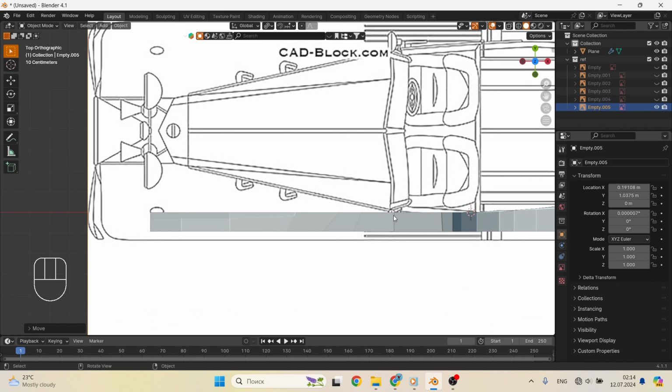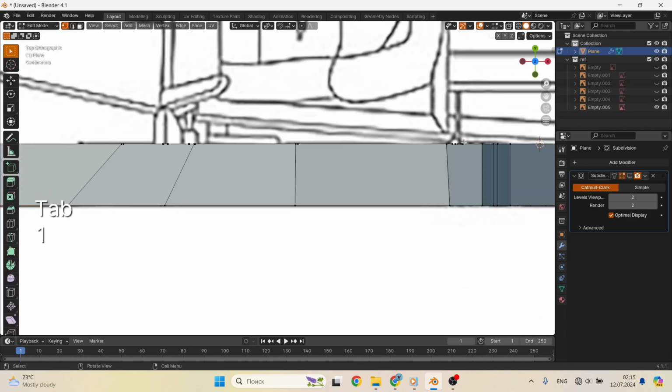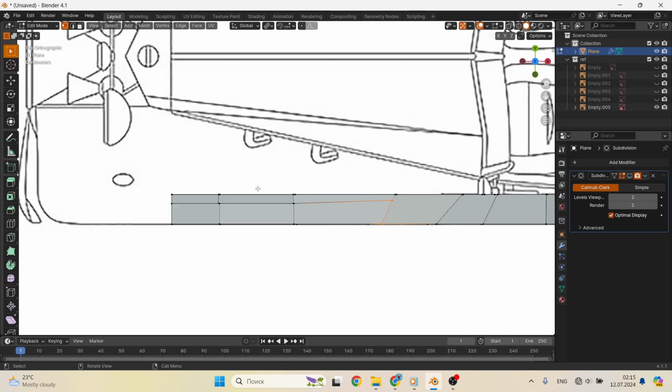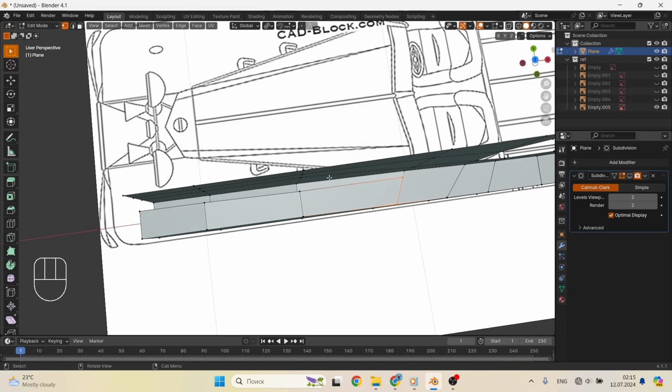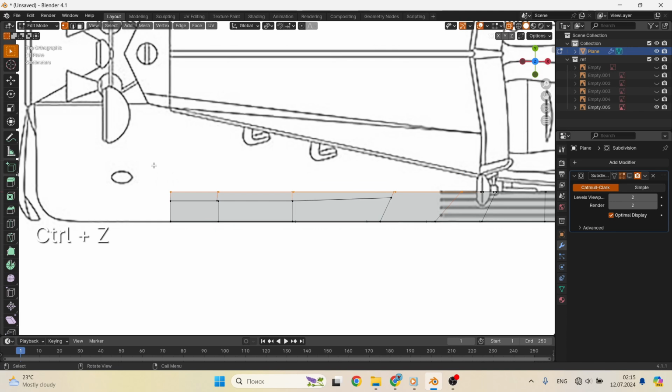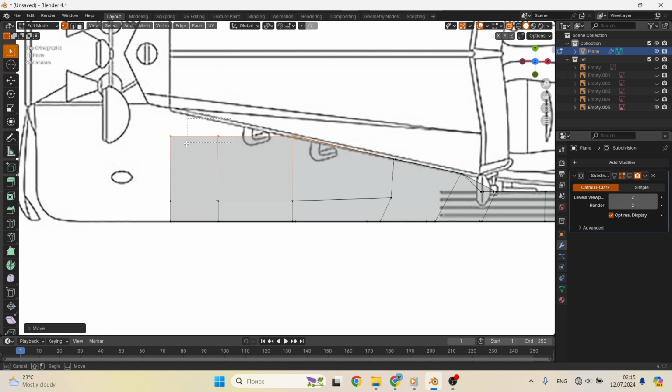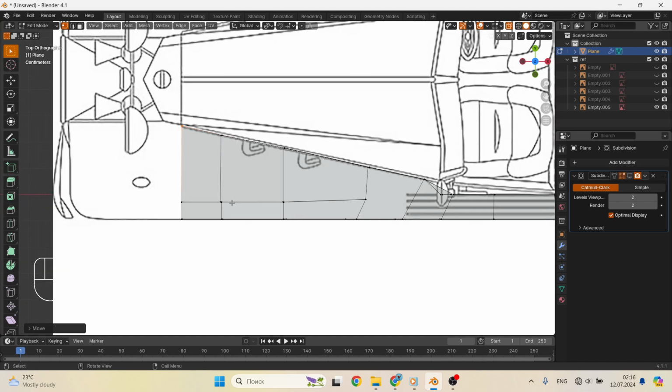6 tips for modeling with mesh subdivision. Here are some tips for modeling objects using the subdivision surface modifier. 1. Always start with building a block model. Creating a block model is one of the most important stages of modeling. At this stage, you determine the scale, style, and appearance of your model. That is why you should always start with a base shape. If you start adding a lot of details, then changing the further shape of the mesh will be quite problematic.